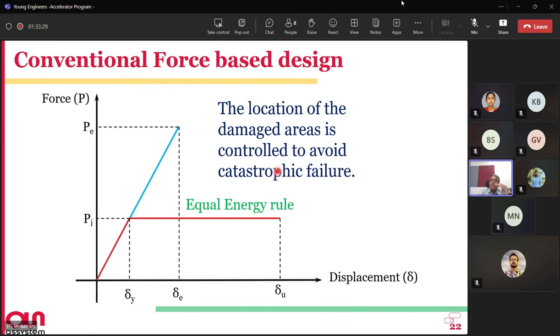So when the ground moves, we have various ways of accommodating the movement. One question is, we can accommodate the relative displacement. That means we know the displacement. We can accommodate it by having a linear force displacement rule. Then, to accommodate the same displacement, we'll come up with a larger design force, right? Now we have also said, if you look at the force against displacement, the area of this triangle between them will give you the amount of energy that is dissipated in one such displacement cycle. We can do the other way around.